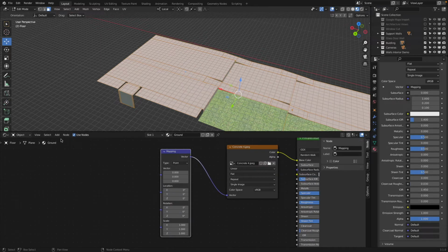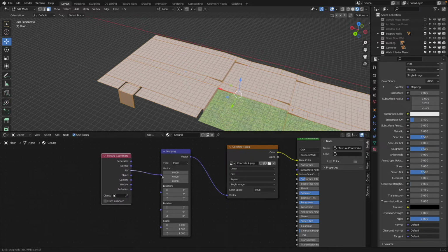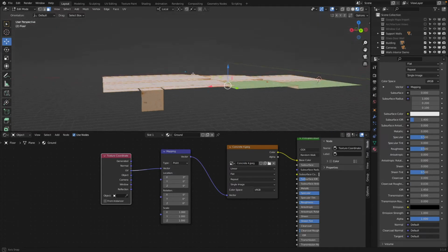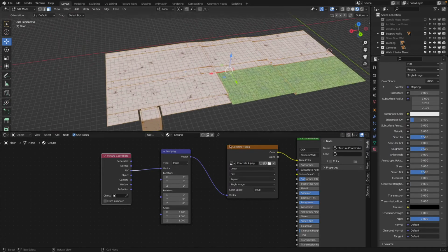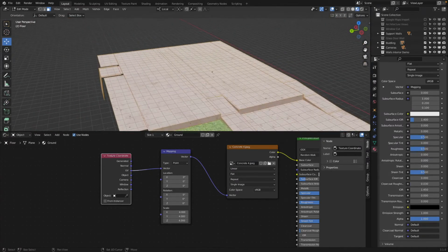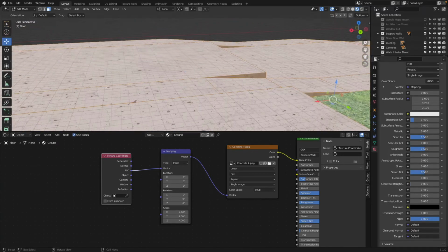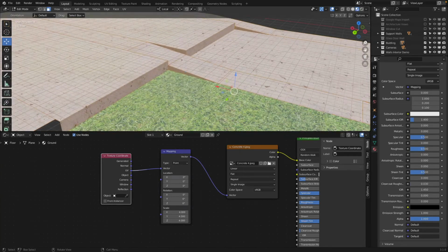And then for the vector, as we said, we need to add also the UV direction. And that's under texture coordinates, UV there. Cool. And then now here we can go in and say scale, then it tiles. Cool. Okay. Very nice.